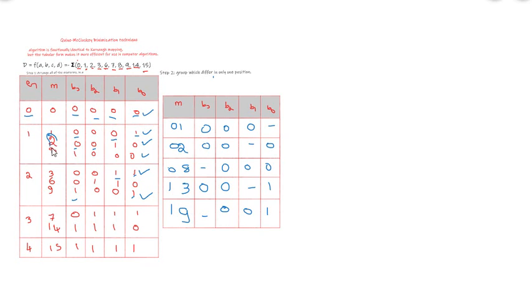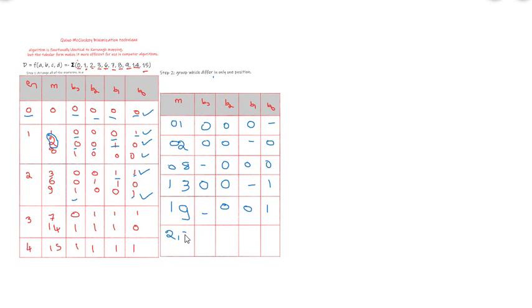Now go with the second term, 2. What do we have to do here? 2 is 0 0 1 0, and 1 is present in B1. Just check whether 1 is present in 3 too. Yes, 3 also has 1 present, so this grouping is possible. We make the grouping in a similar way, 2 and 3. In 2 and 3, 2 is 0 0 1 0 and 3 is 0 0 1 1, so the last bit varies. Both have 0 0 1 the same, and the last bit varies, so it is a dash. Like that we can make more groups. Then 2 and 3 is completed.